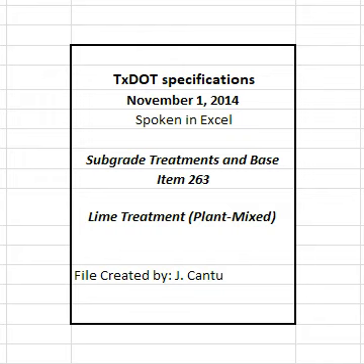2.5 Mix design. Using the materials proposed for the project, the engineer will determine the target lime content and optimum moisture content necessary to produce the required stabilized mixture. The mix will be designed in accordance with TEX 121E. The contractor may propose a mix design developed in accordance with TEX 121E. The engineer will use TEX 121E to verify the contractor's proposed mix design before acceptance.